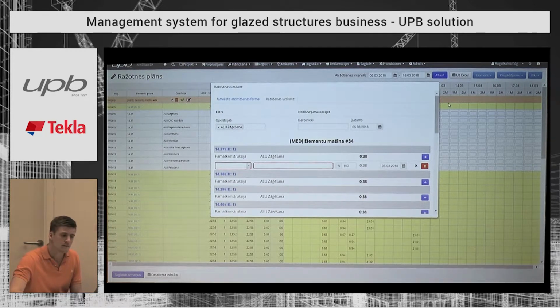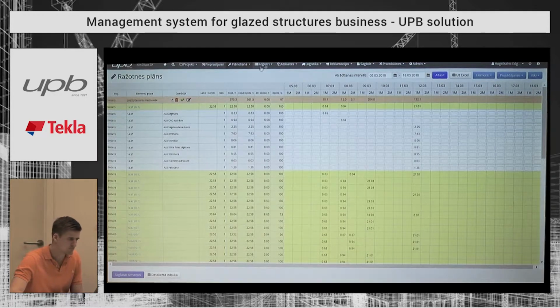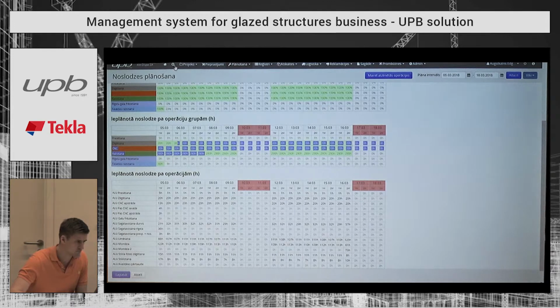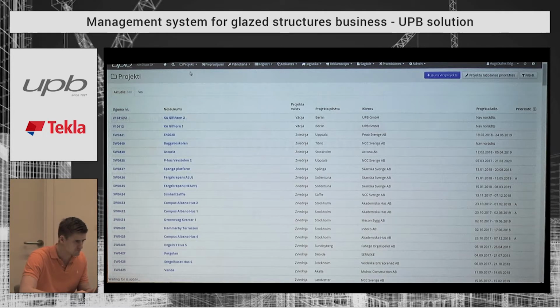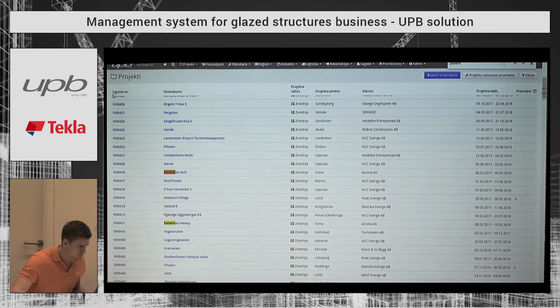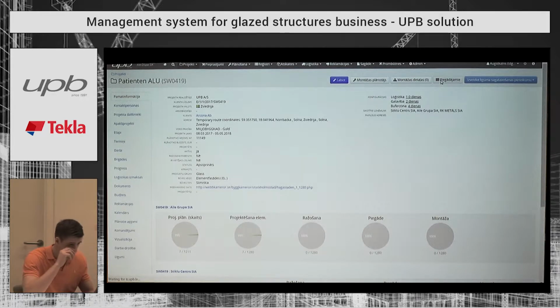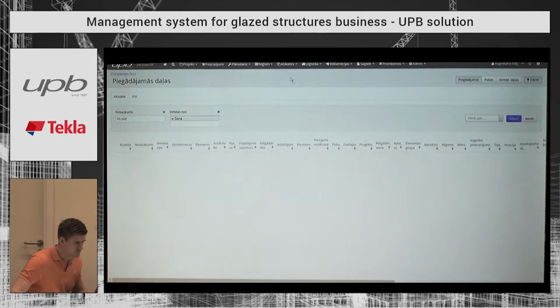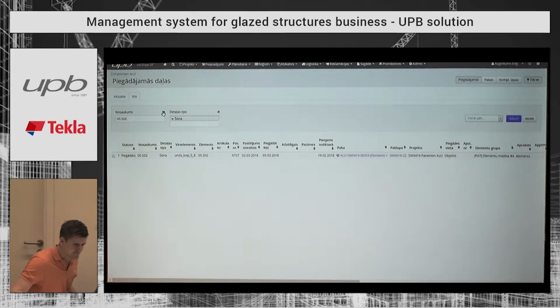It also gives very good feedback to engineers, because, for example, your unit facade consists of something like 600 profiles, and you see in the system how many of them are already cut. For example, out of your 600 profiles, 300 are cut, and you see exactly which are cut. If the architect sends you changes, you can quickly see if the changes can be implemented, or it's too late because we have already cut the profiles. If it's okay, you can quickly change the model, and the system will move those profiles so that you see which profiles need to be cut.